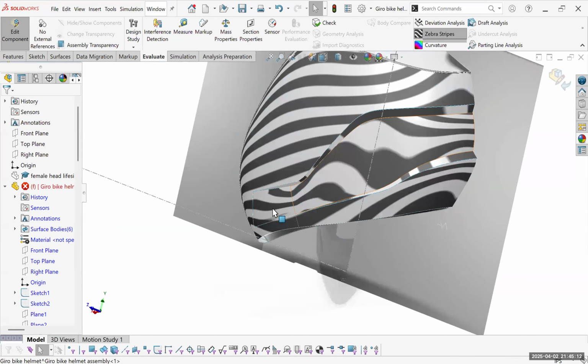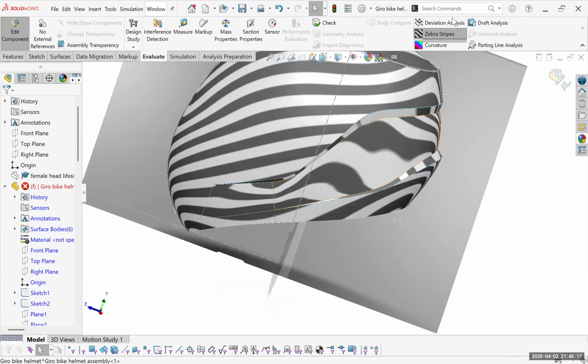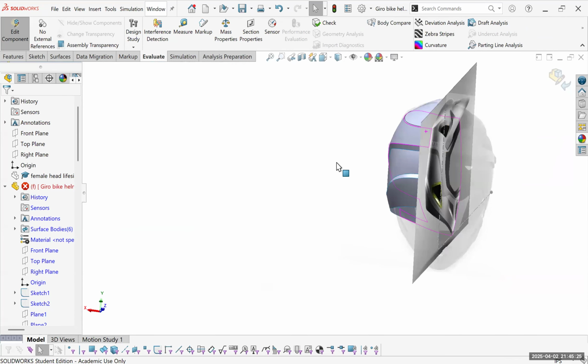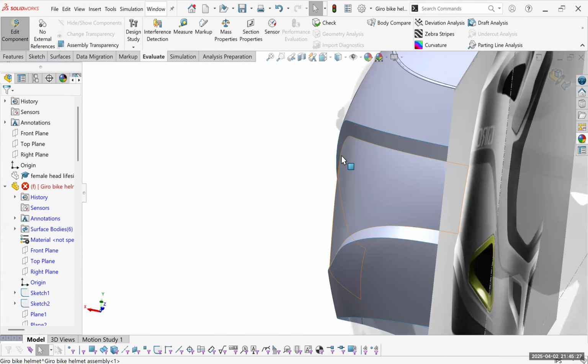Let's recreate that portion. I don't love my 3D sketch over here. I think it's pinching it too much. Another thing we need to kind of be aware of is we're getting too flat over here. So let's go, I'm gonna go before my fill surface. Oh, actually, no, I can't. I need to sketch. I remove that fill surface. Use this to do an extrude surface the opposite way.